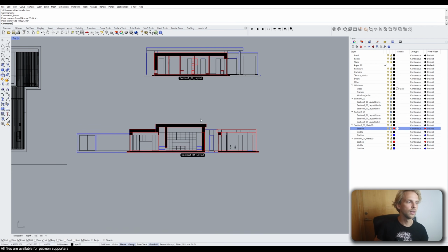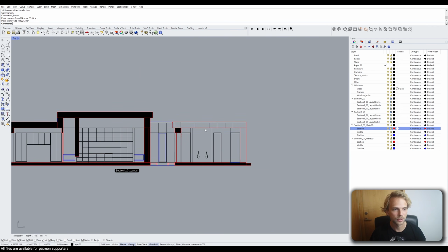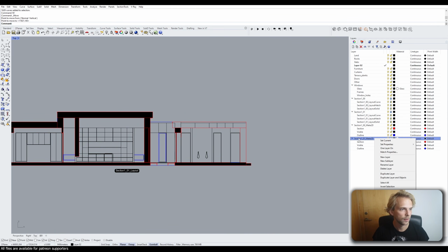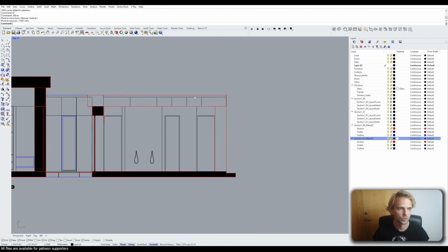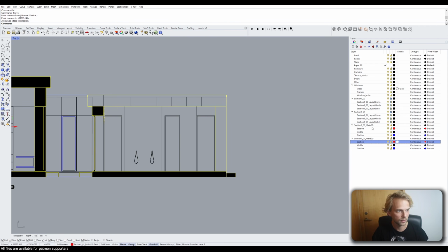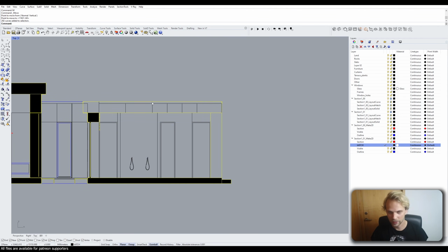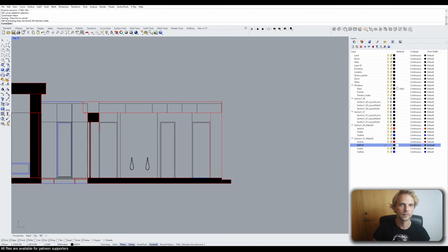Everything else that you are gonna do, you do it manually, which I think is fine. Let's say, oh no, here the hatch wasn't created for the roof and the wall here. We need to add the hatch in. Sure, you just select the objects for this one. Let's create a new layer, call it hatch. Oh, that's a really crappy way of writing hatch, but let's make it our active layer, and I'll just type in hatch. Self-interested, no hatches made. Sure.